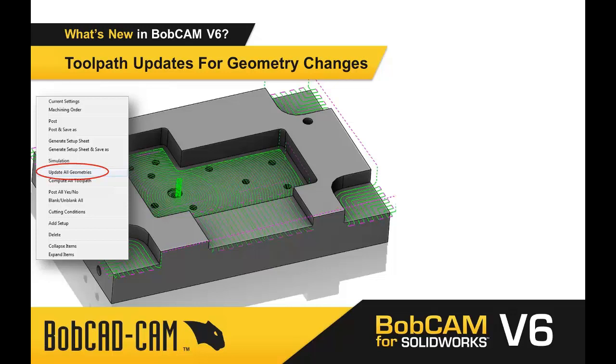What about when you have this part fully programmed, but instead of using a vise, you want to use a fixture plate instead? Let's face it, you're going to need to change your 0 location, or it's likely you're going to need to change your machine setup location. So these are the things that we're addressing. Design changes happen, and your ability to quickly update for those changes makes you a better and a faster programmer.